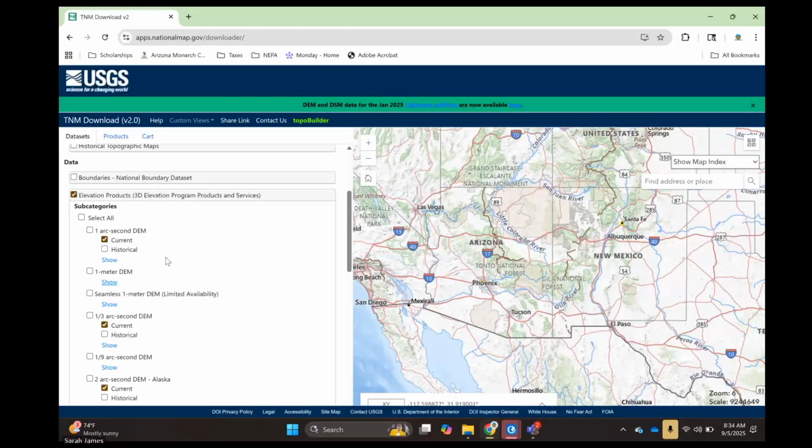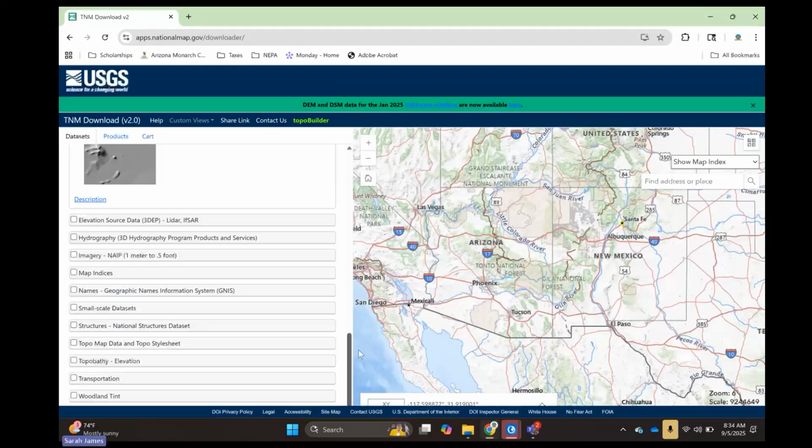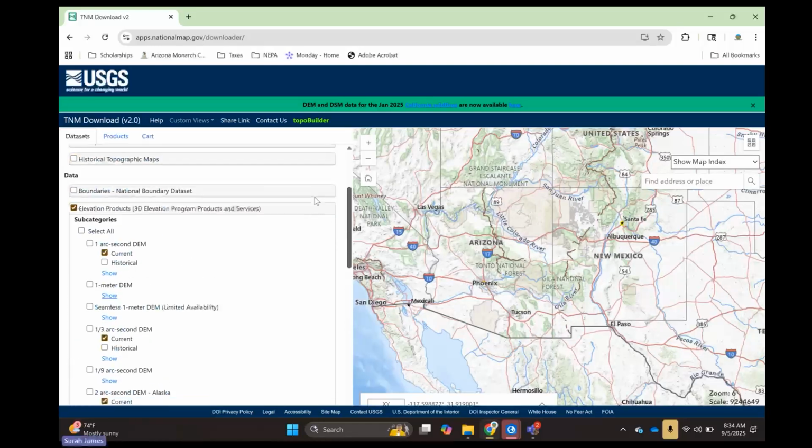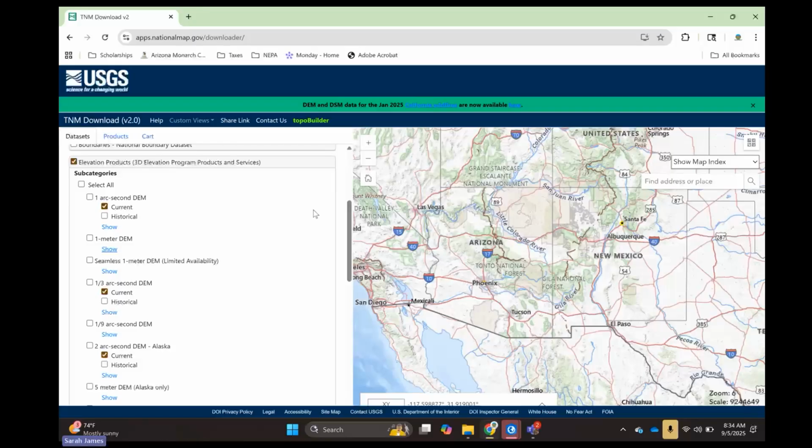And I'm pulling their elevation products right now. However, they have a lot of free products available. They're a really good resource if you're looking for something specific for mapping, they have a lot of info in here. But anyway, I'm going to go ahead and show you. Arizona does not have full LiDAR data yet, but it's working on it and it's all available here. These are DEMs though, and I'm going to show you this 1 meter. Rasters are made up of little squares.